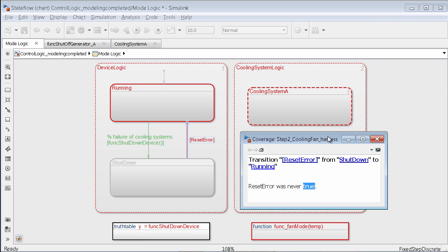So if I don't exercise something in my design, should I be worried? That's a good point. You definitely want all parts of your design to be tested. You want to thoroughly test your supervisory control, and back to why you want to do this, you want to ensure that there's nothing which was not a requirement. Because if this is going to really control a nuclear application or some other safety critical or high integrity application, you really don't want untested parts of your design to exist.